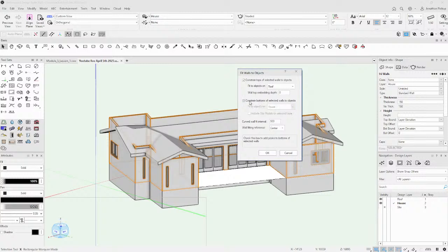So someone did ask me recently how you can create a wall that goes between two separate roofs on a larger project. And the answer to that is that you have two objects that will do the job. So you need the roof on one layer and another object to represent the lower part of the roof, and you can go through that.